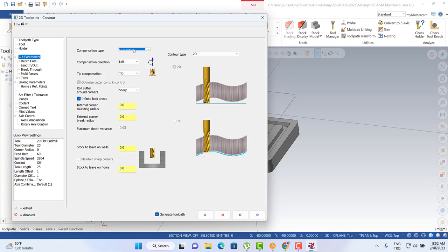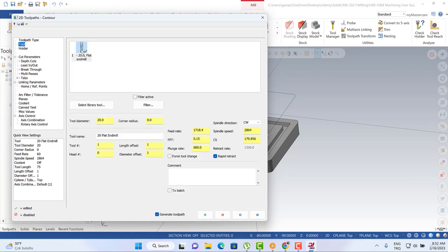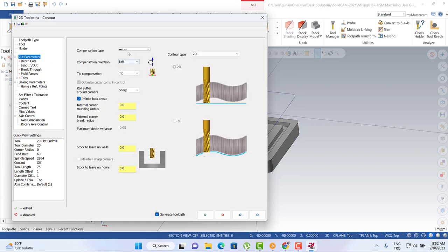If you would like to write your D offset in your CNC, for example, you can turn to the wear activation. And when you select the wear activation, it means that our tool diameter is calculated by MasterCAM, but you can also get some D offset number and you can organize your tool diameter, for example, by using the 0.1 millimeter.